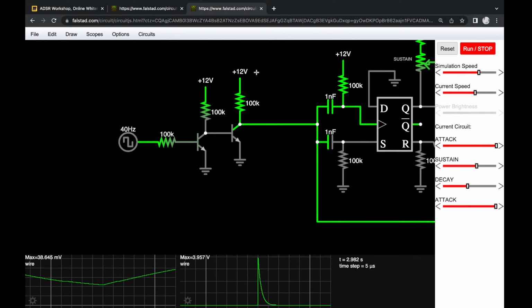This solution has the problem that we have a big resistance over here, right? Whenever this goes high, if it's not connected to anything, we have 12 volts here, but because it's connected to these capacitors and current actually flows, we don't get a 12 volt spike here. We get a little 4 volt spike, simply because we have an impedance here, right? Between the 12 volts here and the capacitors, there's an impedance, and the current that flows through here is limited by this resistor, and that's why we don't get the full spike.